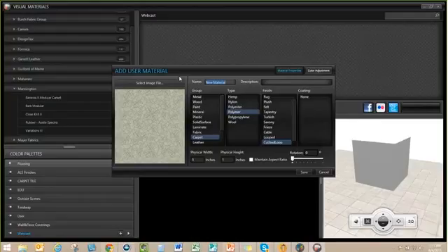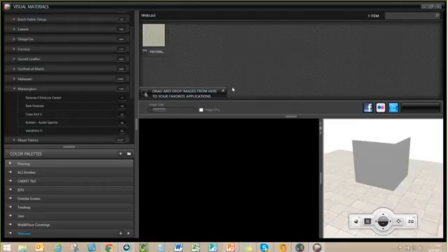I can't remember the name of this pattern, so we're just going to call it pattern wild, and I can choose what it is if I know the type or the finish, and then probably the most important part is to set the size, the scale of that swatch. Now with fabrics, sometimes when you go out to the manufacturer's website, those can be small swatches, maybe they're 12 or 24 or 15 inches. In this case with flooring, I've got a nice big swatch because this is about 6 feet of carpet. When I go ahead and save that, it saves it into my palette.